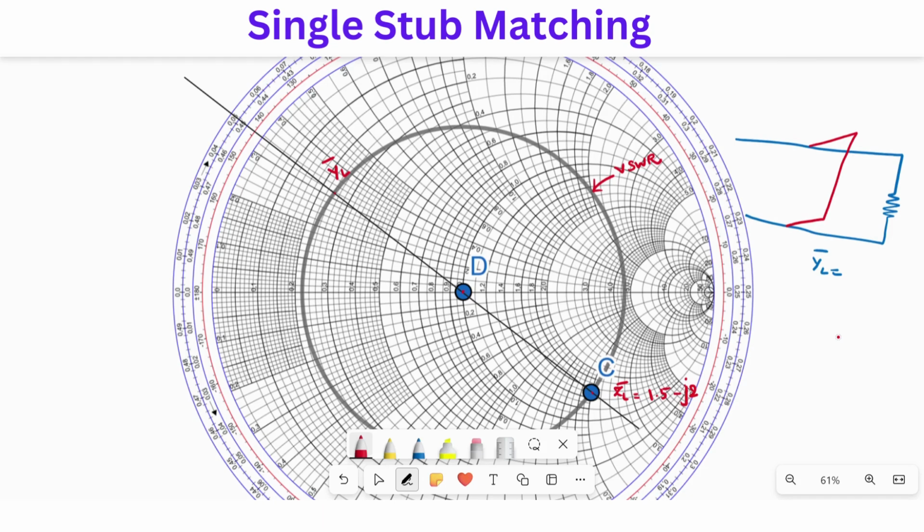To find the value of YL bar, we have to do the following. We have to track the real part on the resistance circle, which is this circle. You should be very careful because you may follow the VSWR circle; you should not do that.